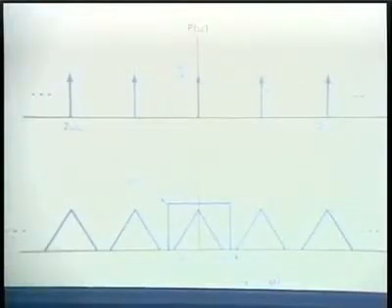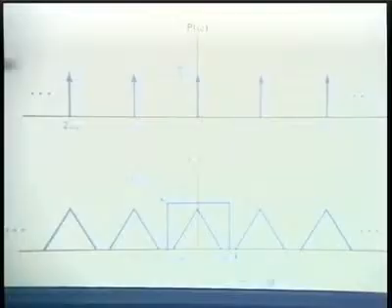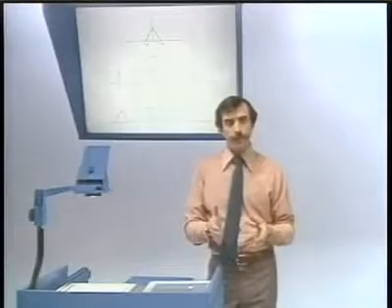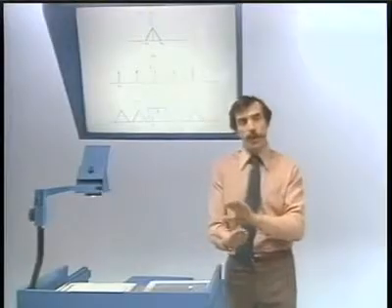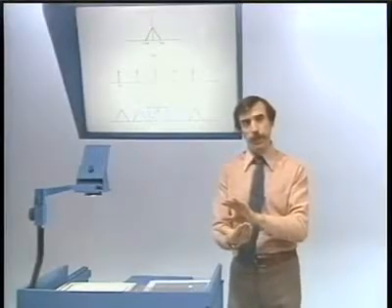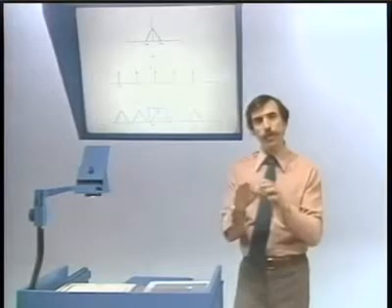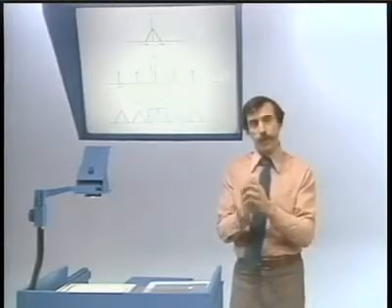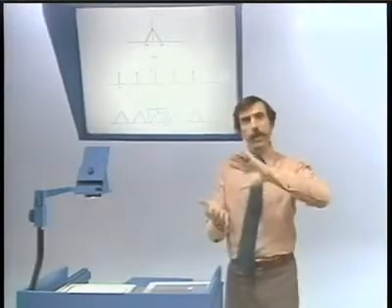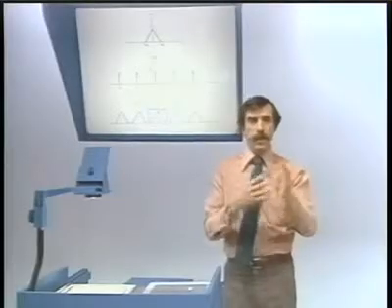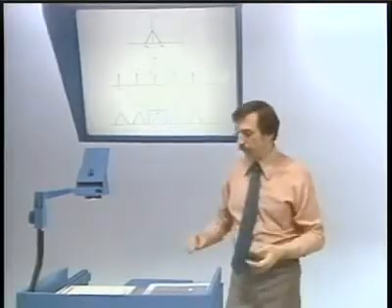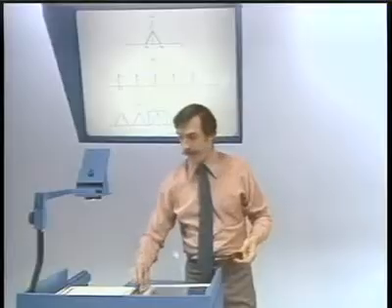And in that case, what this says is that if we have a signal and we modulate it with an impulse train, if we then process that impulse train through an ideal low-pass filter, given the right conditions on the frequency of the impulse train and the bandwidth of the signal, we can recover the original signal back again.